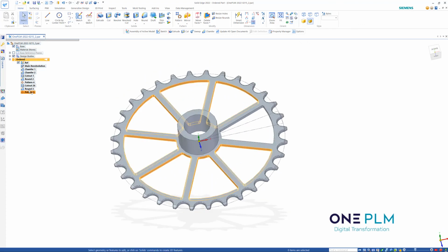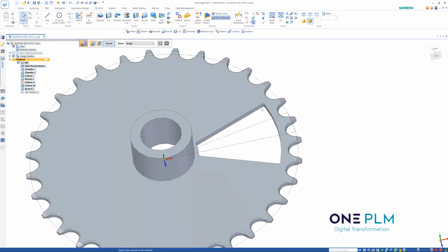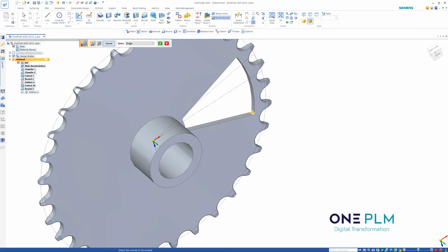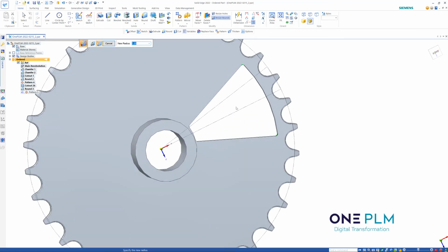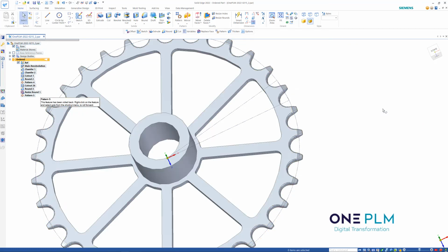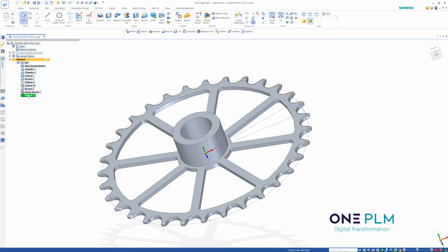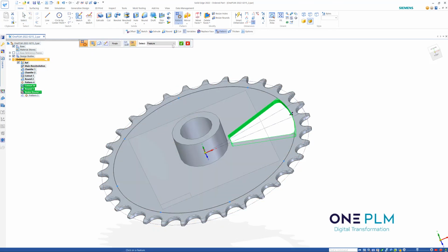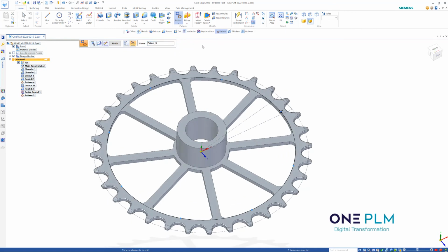I might go and do it though, so I'm going to go back to my round, and I'm just going to resize those two. Let's go 5. See what that looks like. No, let's go 3. That looks fine. And then we'll go back to our pattern. So if we've done the shortcut, we'll choose that F4, and we need to go and add that resize to the pattern as well. So back to our first step, add the resize, accept, and we're looking good.